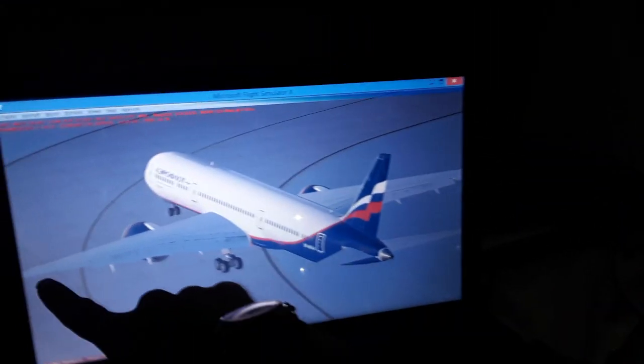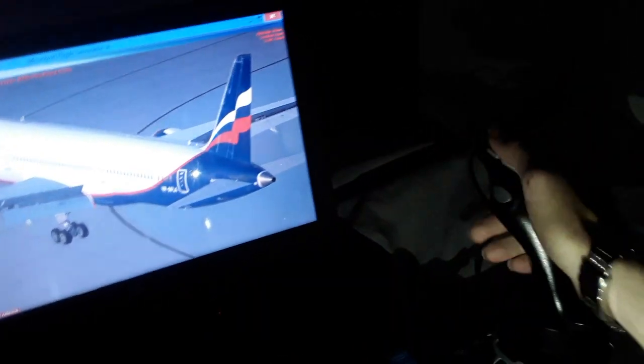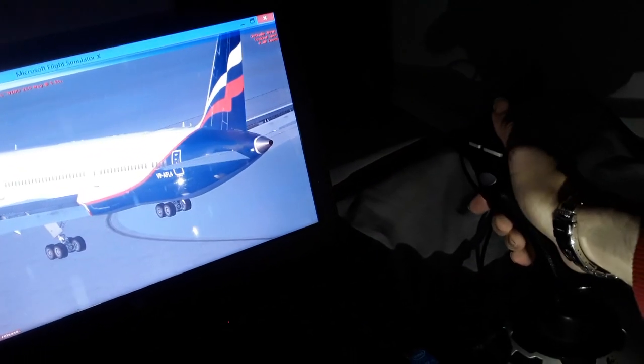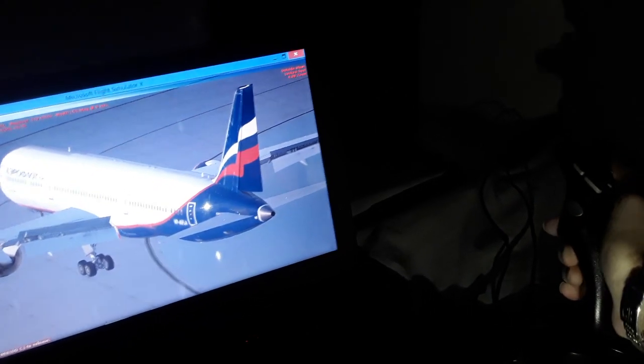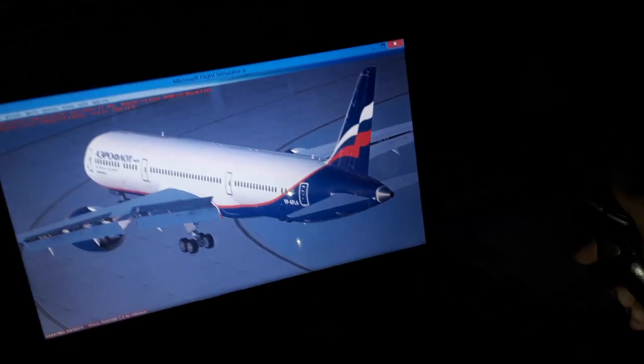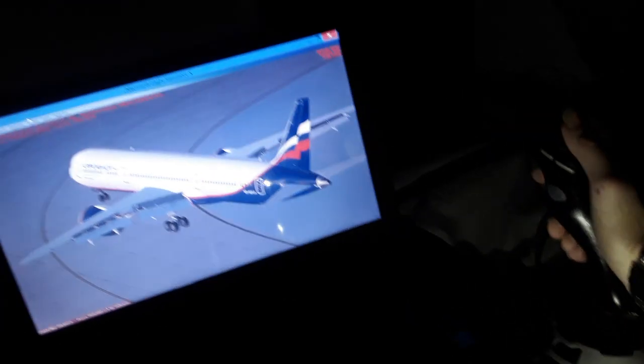This is also the lateral axis from wingtip to wingtip. It is the pitch axis for the elevator, for making climbs and descents of the aircraft like this. So you can climb and you can descend like this. To climb, use the elevator up. To descend, move the elevator down, the yoke down. So this is the main explanation of the flight controls and the aerodynamics of the aircraft.